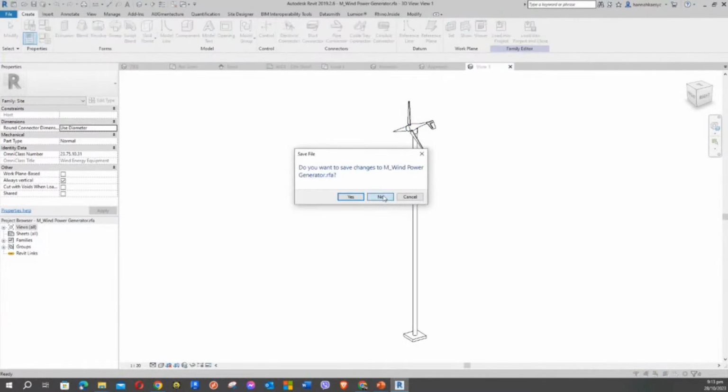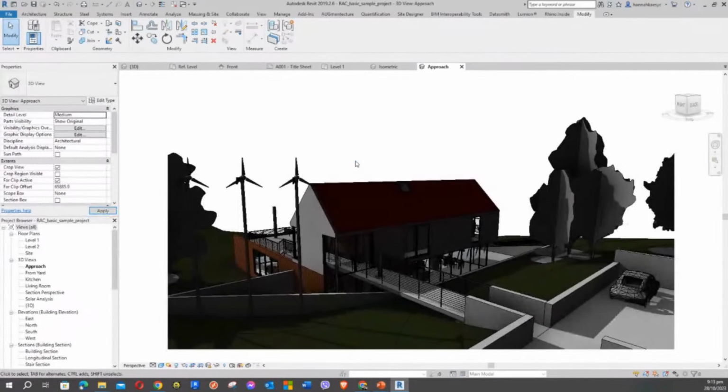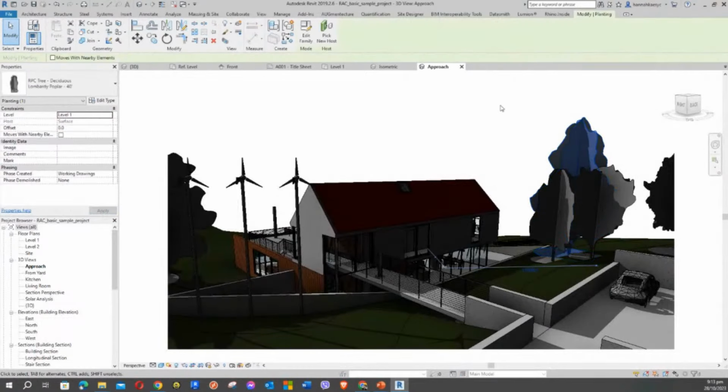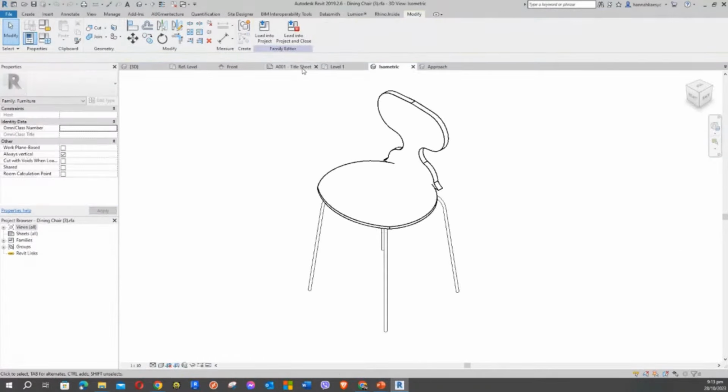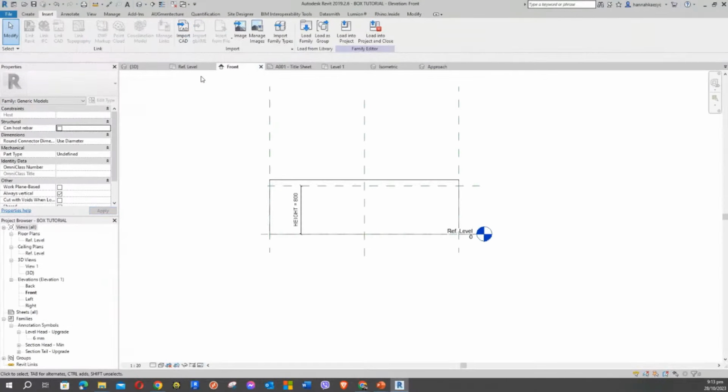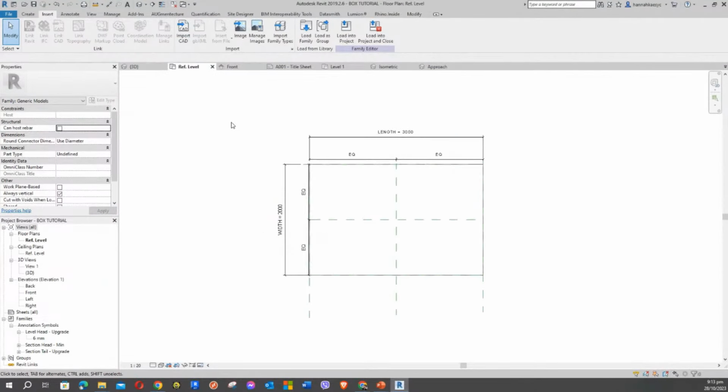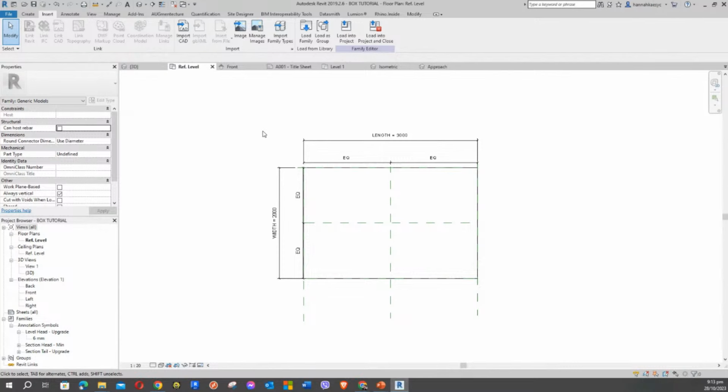Most of that is probably Revit, inserted using some third-party plugin, a third-party 3D CAD file or geometry, and then inserted as a family. So it is more advisable to convert it into a Revit family first, just to have that identity.